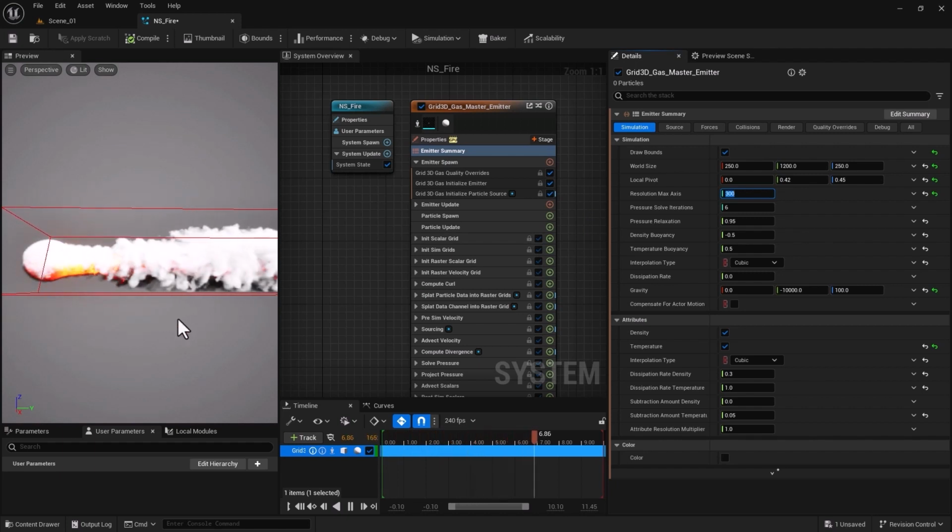You can go up to 400, 450, but I noticed after 500 cells, everything becomes very unstable and even hard to process. So go easy on this. Never put a crazy number like 1000 in there. Otherwise, you're at risk of crashing, not to mention the scene is going to slow down significantly.